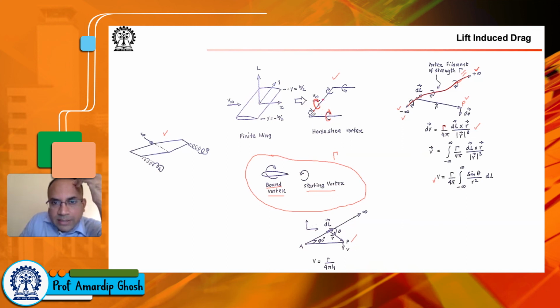So you see that this is known as the semi-infinite vortex filament, and this one is a straight vortex filament. Okay, so this one goes all the way, eventually you actually close it up with the starting vortex line. But however, you can model it as semi-infinite from 0 to infinity. It depends on where your starting vortex is, but the effect of these elements gradually decreases as you go far away from this wing location.